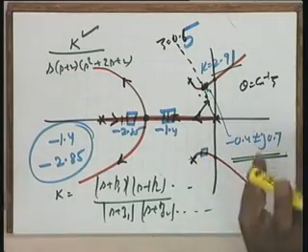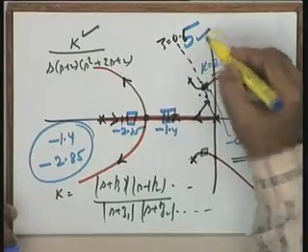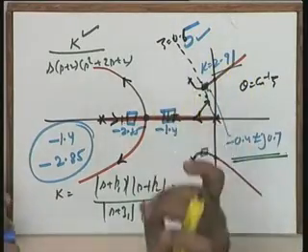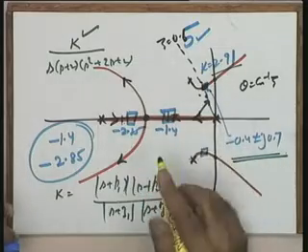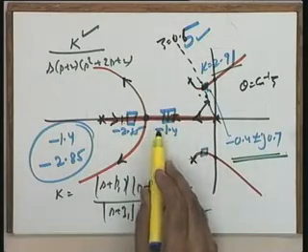So naturally this total analysis will come from simulation, but you have a rough idea that whatever peak overshoot you expect corresponding to zeta equal to 0.5, the actual overshoot will be slightly different than that because of the presence of this pole, not more.